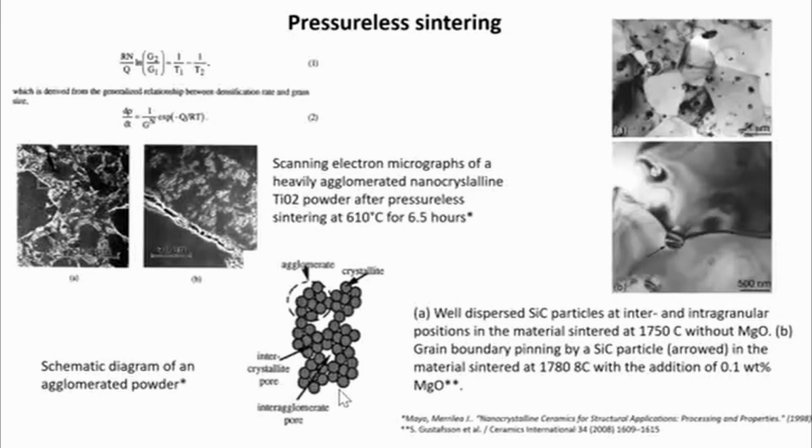Nanocrystalline ceramic is made primarily by the compaction and sintering of ultrafine particles. A brief look at the theoretical literature on the sintering of ultrafine powders tends to be very encouraging. Rules of thumb such as the Herring scaling law would predict that nanoparticles should sinter easily at low temperatures.